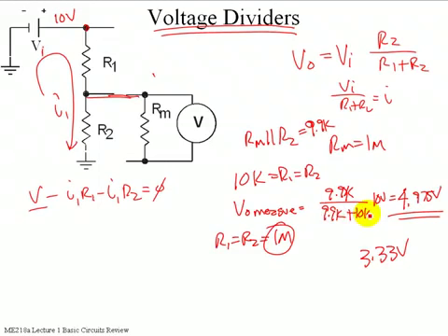And so if we're trying to make a measurement with an instrument whose internal resistance is the same as the elements in our circuit, we're going to end up making gross distortions of what the situation is in the circuit just by adding that resistance measurement. That's why we try and tell you to keep the values of your resistors down in the tens to hundreds of kilo ohms range, not let them get up into the mega ohms.